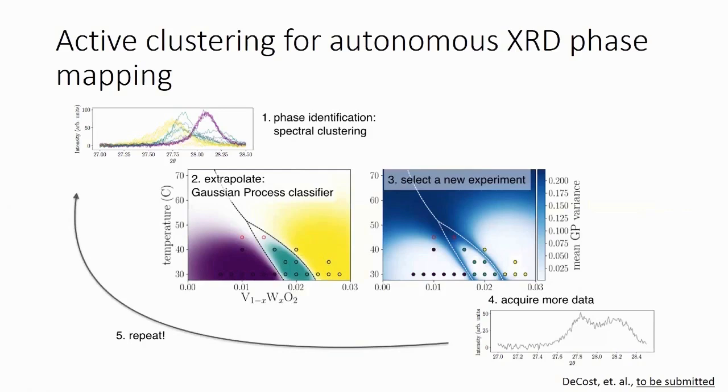What Brian DeCoste has been doing over the past year or so is training a Gaussian process classifier to take diffraction measurements as a function of composition and temperature, and to accurately map out the composition ranges using uncertainty in terms of the classifier. If I were to dense scan this vanadium tungsten film, I'd be talking about doing 2-3 days easily of constant X-ray diffraction measurement. As it stands right now, we're able to create these types of phase maps in less than 12 hours.